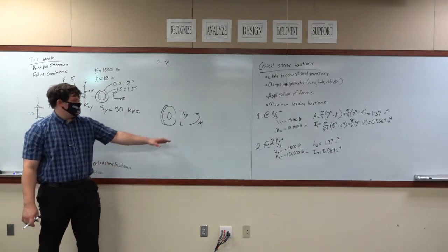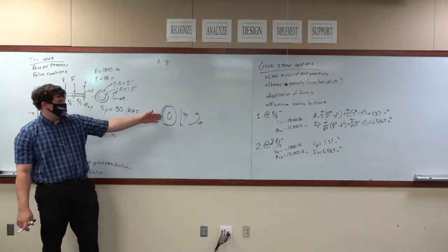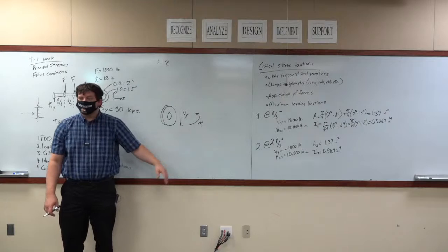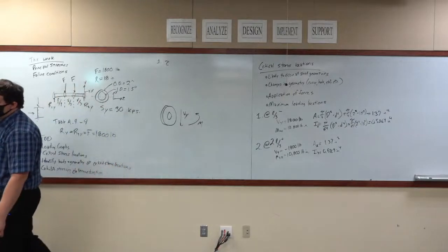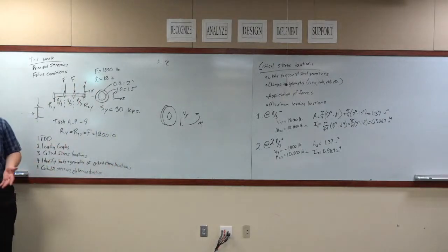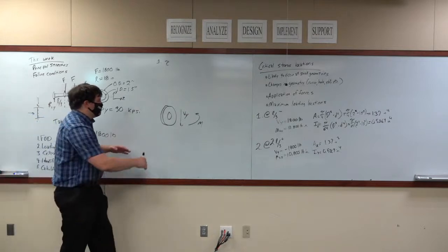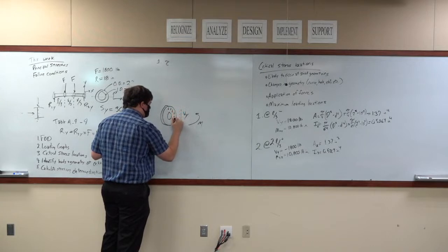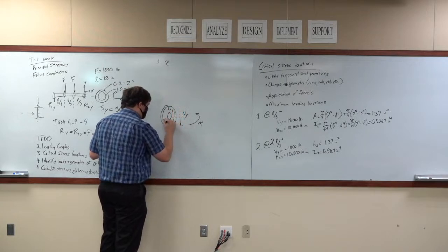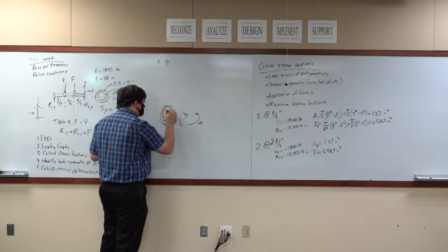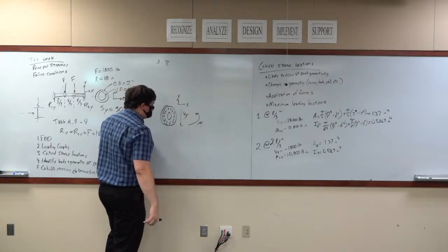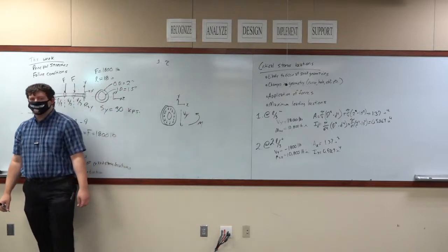And it means that the sum of all the forces here are going to sum to a bending moment equal to M. That's what it means when we start taking a cross section. So we're carrying little amounts of force in this direction related to Vy. What direction is that? Remember, this is the YZ face.